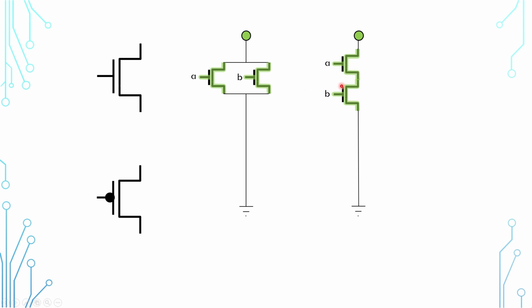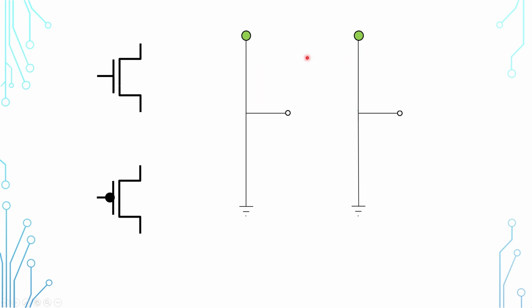Having said that, these two circuitries are not sufficient to form a digital logic gate. Do you know why? Now let's put an output port here to understand what's going on. When we enable the transistors, practically this becomes a short circuit. While this is a live connection, we cannot really tell if the output port is driven by the high voltage here or driven by the ground here.